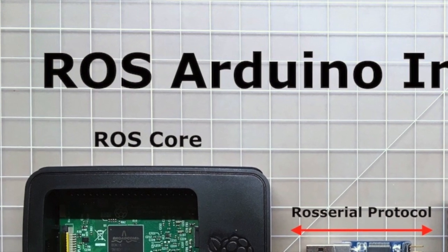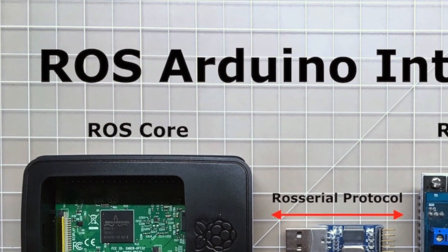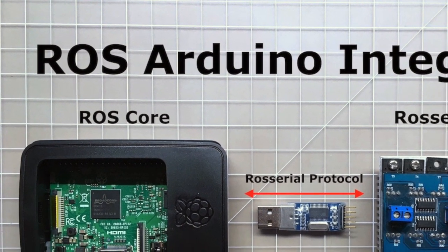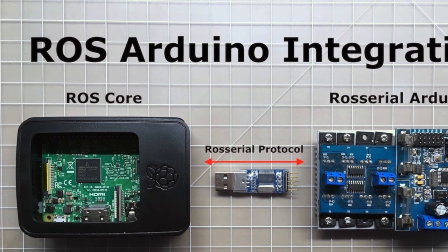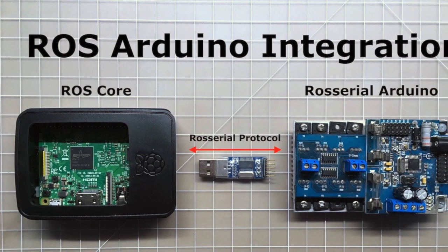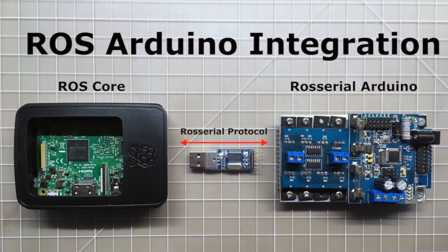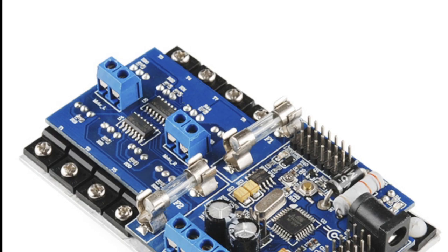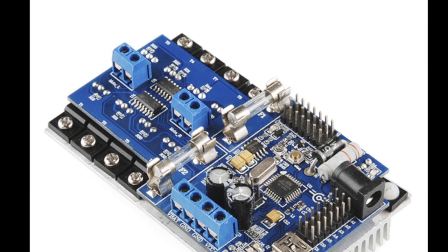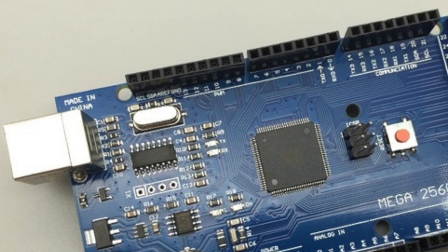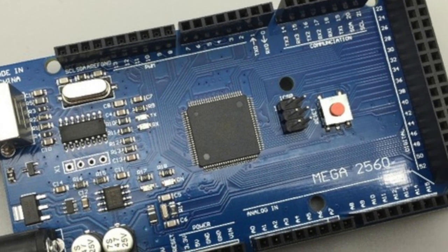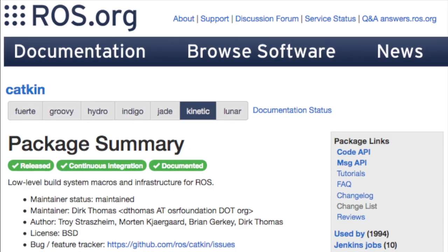ROS has a good messaging system that uses a publisher and subscriber model. My project requires an Arduino to talk to a ROS network. ROS serial for Arduino exists to enable such communication. My previous attempt to use ROS serial on Atmega 168 was not successful due to the 1 KB SRAM limit on the Atmega. This time, I will use Atmega 2560 with 8 KB of SRAM.